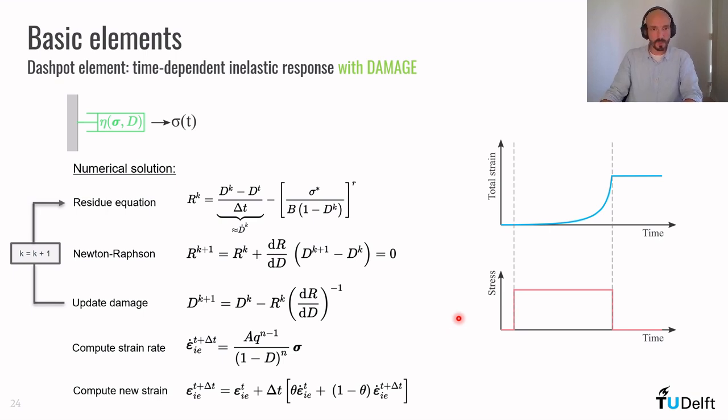We are assuming that we know the stress in this case, and we want to compute the corresponding deformation, because that's usually the case when we perform triaxial tests. When we perform a triaxial test in the lab, we apply a certain stress condition. So we know the stress condition, and we want to measure the deformation over time. We apply the stresses and we measure the deformation.